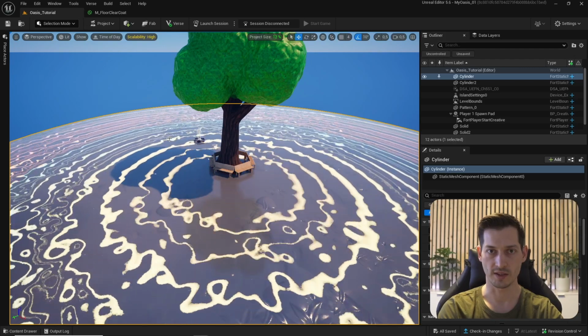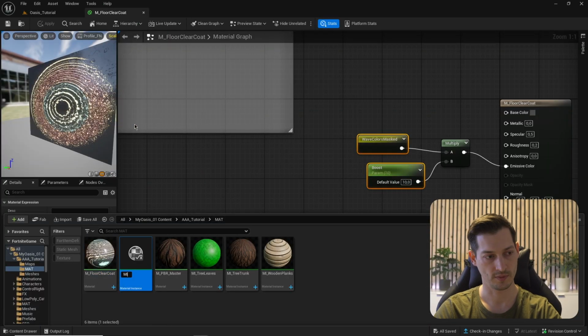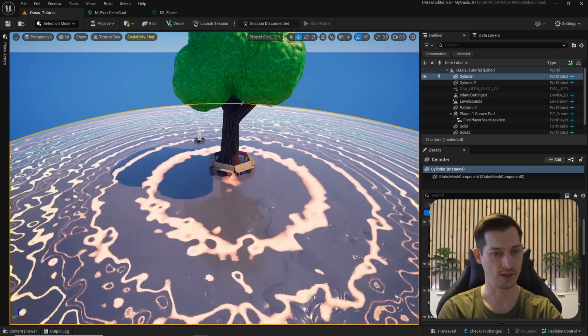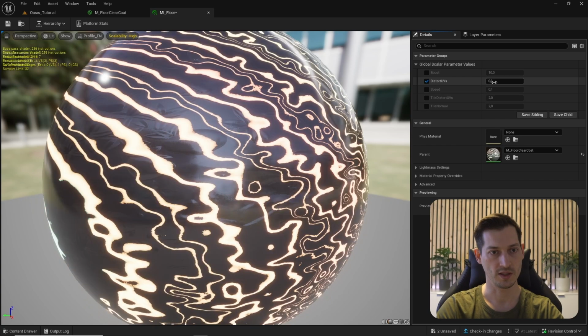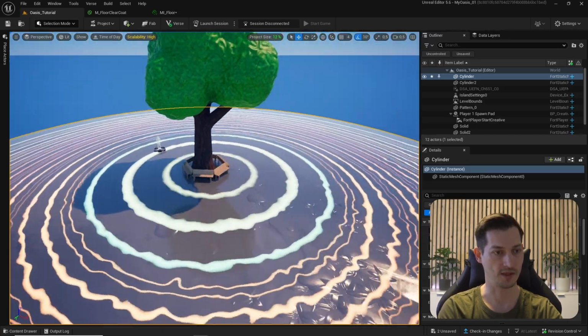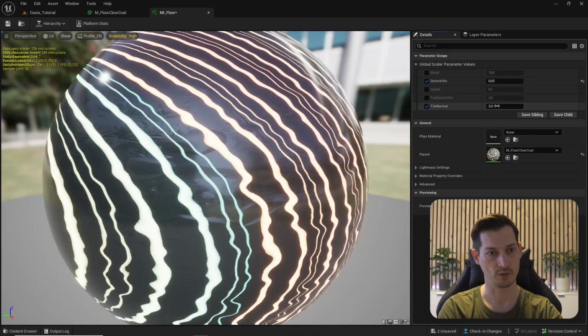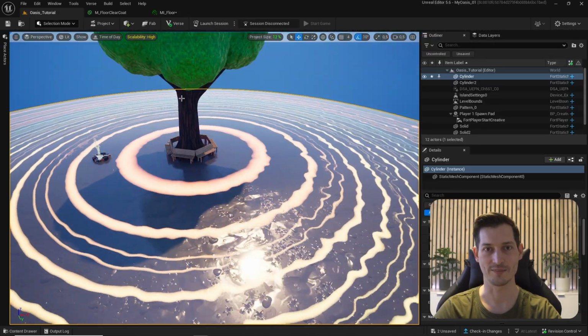So let's create a material instance and adjust some parameters. So right click, create material instance, mi floor, double click to open, and apply this one here instead of the original material. Under distort UVs, let's say 0.05, that's better. Maybe even lower, 0.02, and that seems fine for me. Let's adjust also the tiling of the normal texture, so tile normal, let's say 8, and this looks better, I would say. Alright, that's good for now.